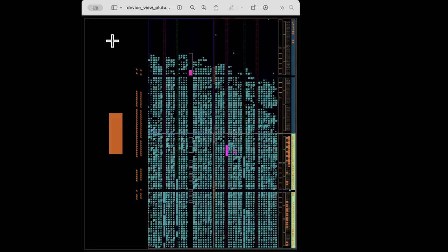With forward error correction, we've taken out a lot of redundancy in our signal, but we're putting back in redundancy that makes it so we can detect and correct errors. Interleaving scrambles the bits with respect to time. Randomization scrambles them with respect to value, but interleaving moves everything around. So interleaving is key. It follows the forward error correction, and what it does to make your signal even more resilient to noise is this: a burst error, or a crash of static, or something that happens that wipes out many symbols, many bits in a row.